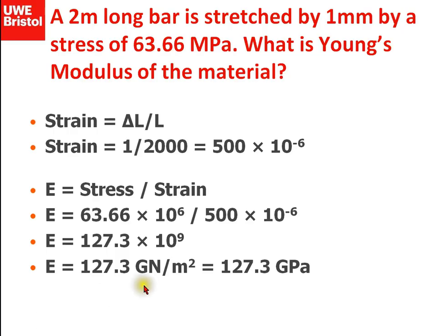Okay, that's the end of my slideshow. So that's taking what we did in the lecture, and we've gone a bit further. Don't panic too much about some of these terms, because I did all the essential stuff in the lecture. The essential stuff that you need to know is the definition of direct stress, the definition of direct strain, and that Young's modulus is stress over strain. So they are the three essential equations that you need to know for your test.